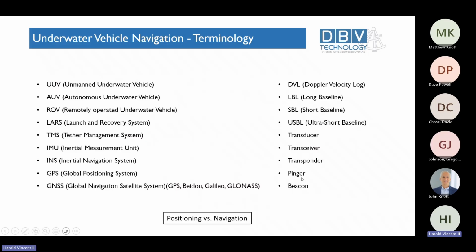And then the last two terms are a pinger and a beacon. And I distinguish between the two in that a pinger is an acoustic device that goes underwater and it simply transmits an acoustic signal at some regular interval. And that transmission of the acoustic signal might be synchronous. It might be synchronized, say, to a GPS clock, or it might be asynchronous. And depending upon synchronous or asynchronous, that would have some effects on how you perform your underwater acoustic positioning, as we'll talk about.